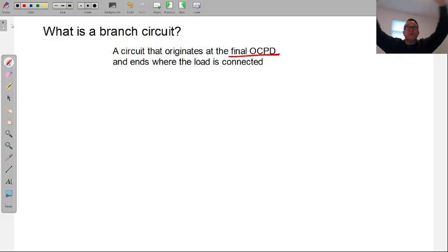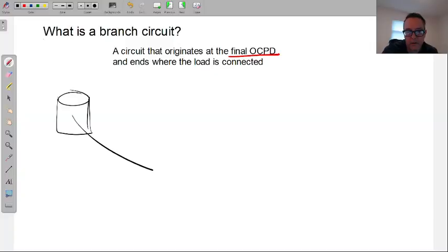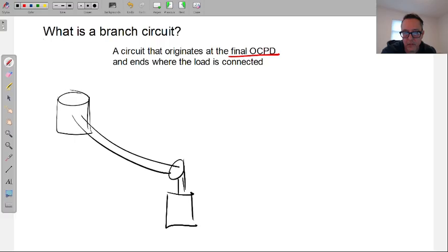So, the power that comes into the building. To describe a house, the outside transformer, for example, and the wires are coming down, we have our weatherhead coming into this panel. These wires here, this is a circuit being brought to us by the utility company. This circuit is a feeder circuit. Now in this particular case, it is also a service, meaning it is bringing power into the building, so we call that the service. But these are feeders, and this is a feeder circuit.